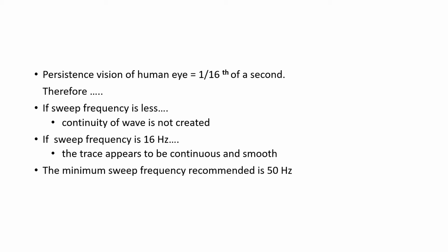So we have to use a low frequency sweep generator while measuring low frequency signals so that flickering does not occur. The conditions for flicker-free waveforms are: use low frequency sweep generators, or use the CRO in automatic or external triggering mode. Last one, connect the signal to the vertical input and the external trigger to the external triggering input so that we get a flicker-free waveform.